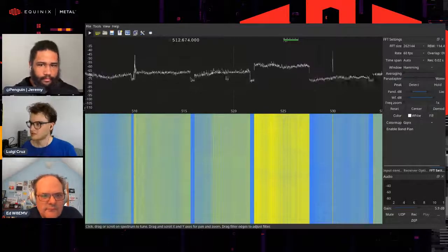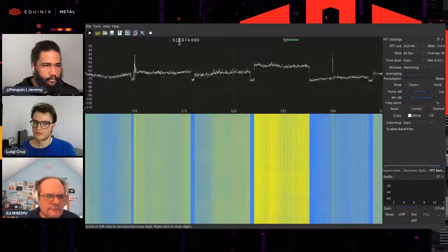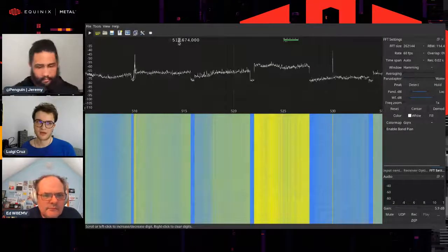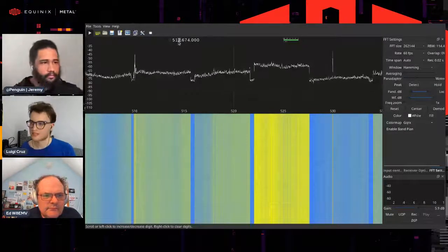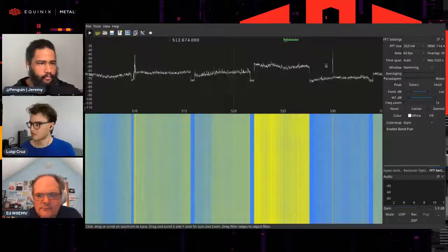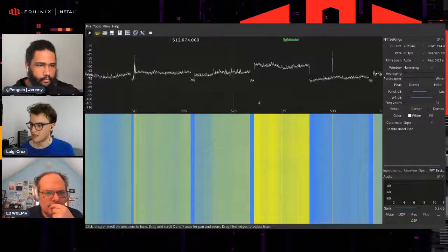So each channel here has 6 megahertz of bandwidth, and you can send up to 4 streams at the same time, 4 screens, like 1080p streams at the same time, using the single carrier that is this box here, separated with a 500 kilohertz spacing between all the channels.